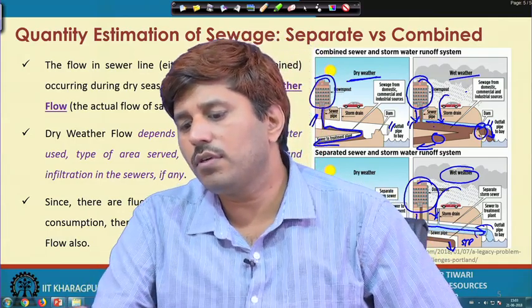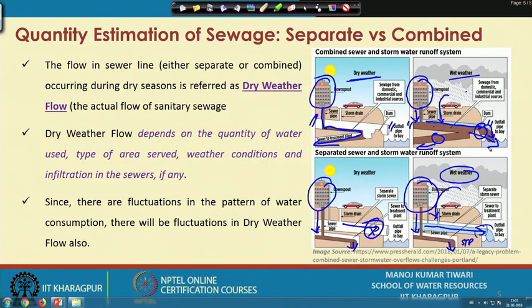So, either you discharge a lot of pollutants into your natural rivers, or because your treatment capacity is very limited, whatever you are channelizing to the treatment plant has a reduced load because of the dilution. So, your treatment system again may not work appropriately because the pollution load has decreased, and most wastewater treatment systems are of biological nature.